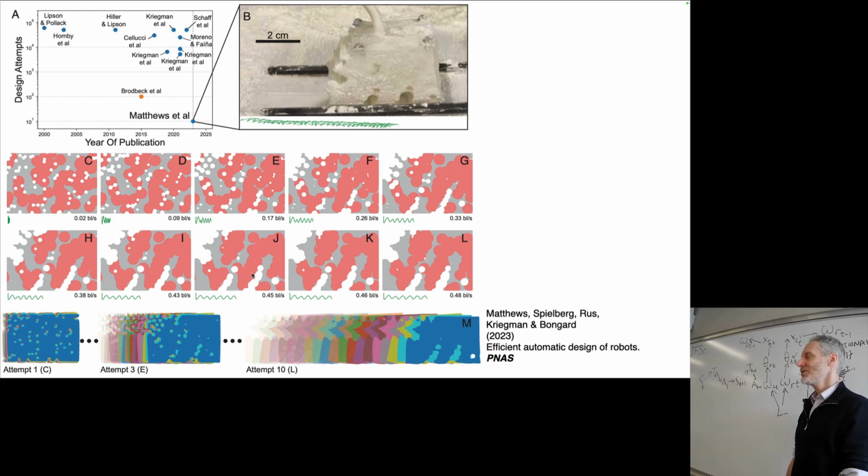The dragon skin? Dragon skin. It's a particular type of silicone rubber that's liquid at room temperature. We pour that in, and the liquid spills out and fills all the gray parts. In the mold, imagine there are cylinders poking up from the bottom, pointing upwards. That cylinder resists the dragon skin, and the dragon skin flows around it.